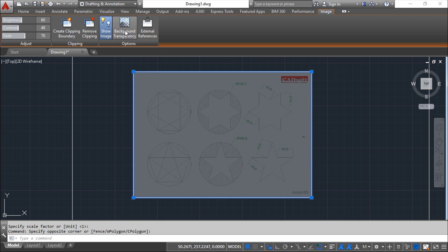We have also the possibility to turn on or turn off the background transparency, but in this particular case there are a couple of add-ons with this, because the image itself has to be prepared. For example, when you have a GIF image, you have to have the preparation in the sense that the background of the image had to be removed when you got it inside AutoCAD.